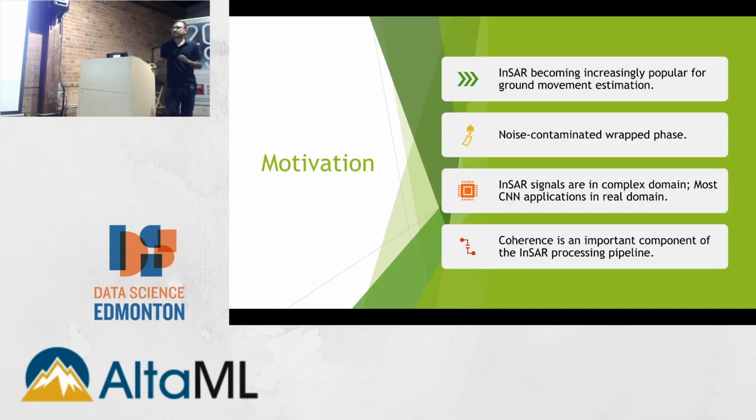Now, you can use satellite images for comparing two images of the same mining site taken at a difference of, let's say, 1 or 2 weeks. And if you take a difference of those images, you can quantify how much the ground has moved. It may be that the ground is coming up or coming down. And if the rate of motion is beyond a certain threshold, there's the risk of landslides, and people working in the mines may be in danger. So we want to raise an alarm.